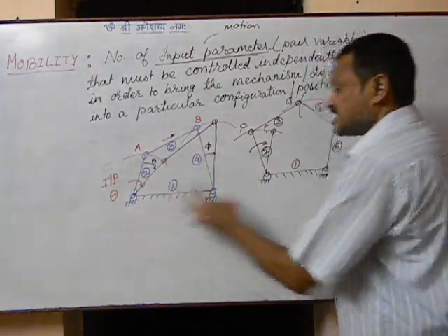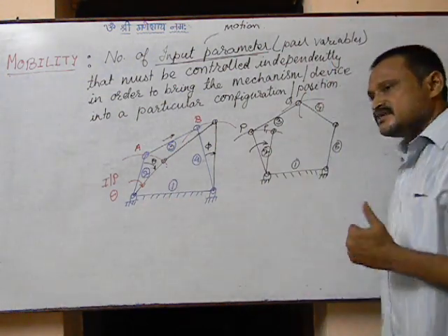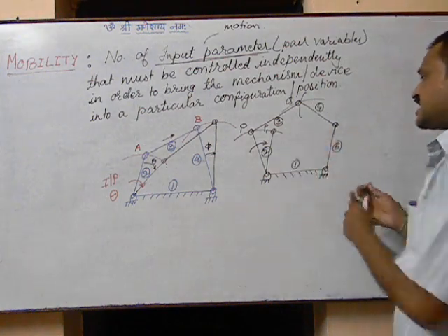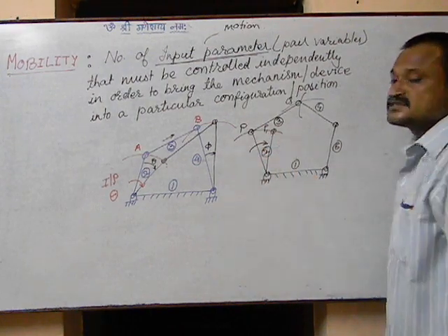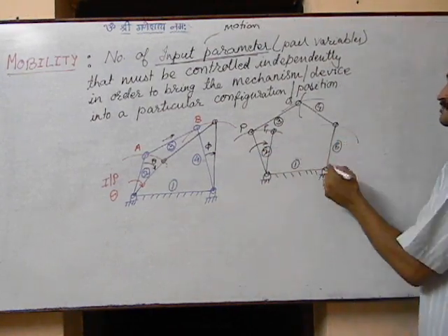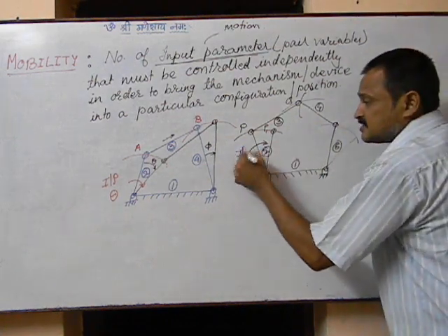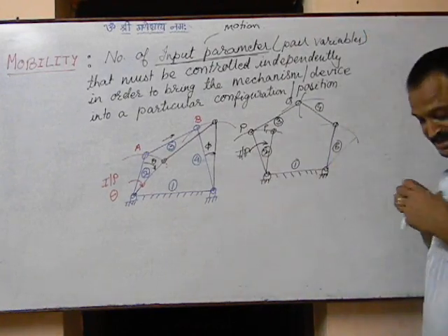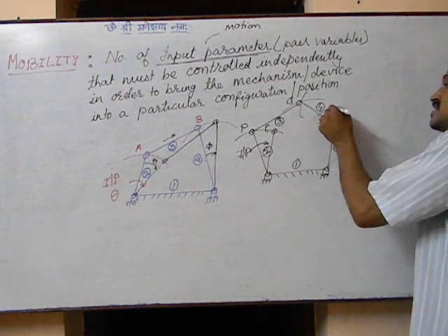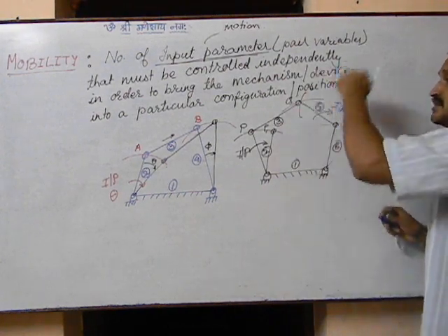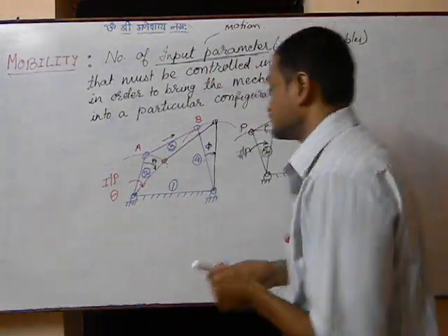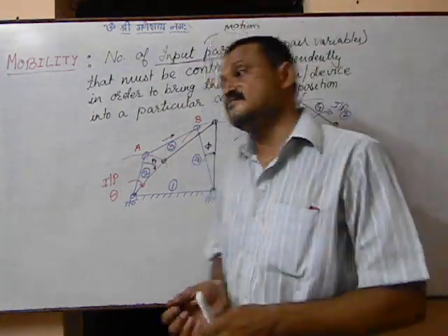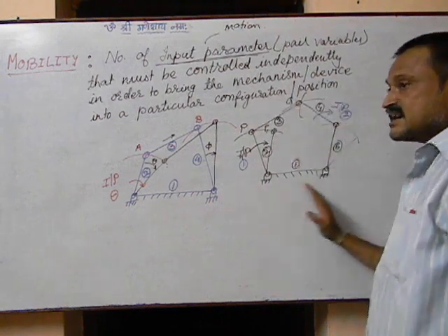See, we have talked about kinematic chain and non-kinematic chain. But if I have a mechanism wherein I need 5 links, there I have to ensure that when I turn this by say theta, I want this to turn by phi. But I cannot control this output with the help of only one input. So maybe in that case I need to provide another input, which has to be independently incorporated in the system. So I need input number 1, I need input number 2. Then only it will become a kinematic chain, right?